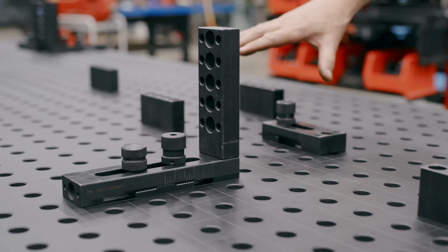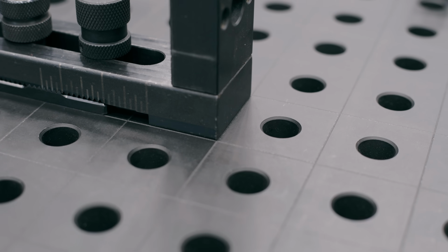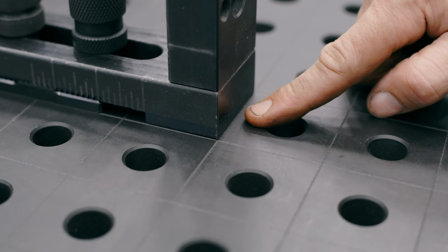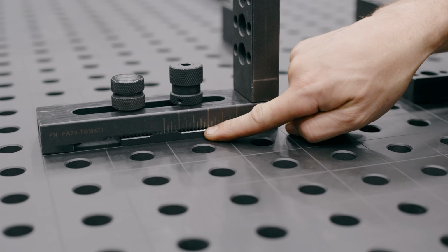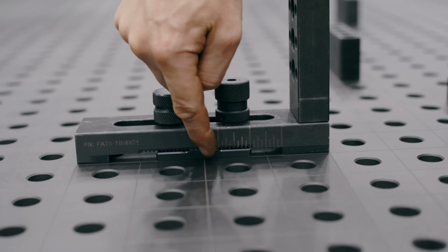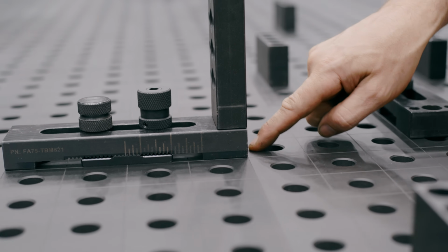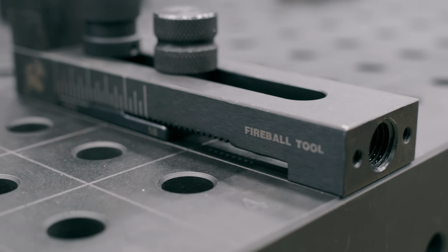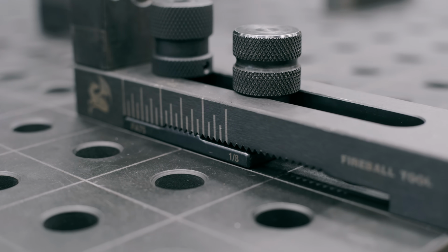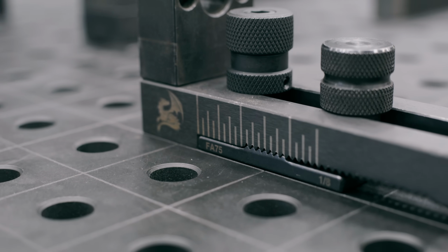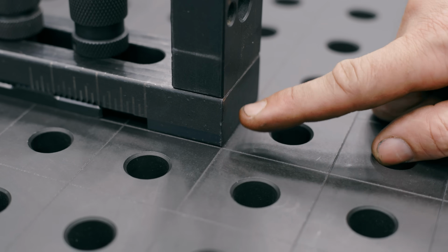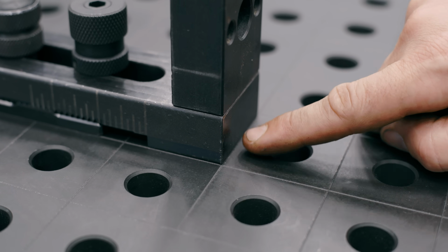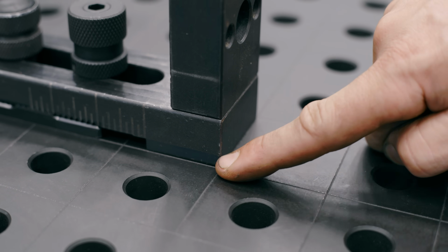So we're all done with the fixture setup for this demonstration, but I want to bring you in close to just show you how dialed everything is. So this table has a scale in it, and you can see we're matched up 1 inch extended. So the teeth do all the locating, and we can visually confirm that it's where it needs to be off the grid line. We have a lot of system checks built into the system that really make sure the block is where it needs to be, and you can identify it if there's something wrong. And another neat thing is you notice our blocks are 2 inches wide, which is really nice. So we have full coverage across the entire table.